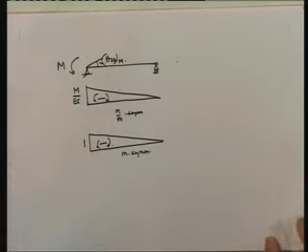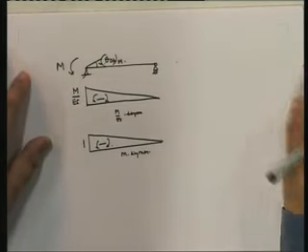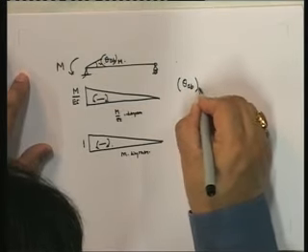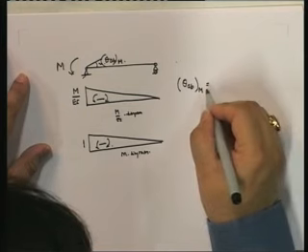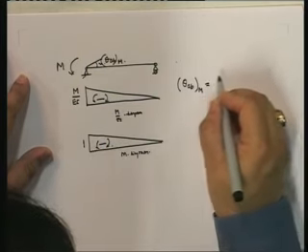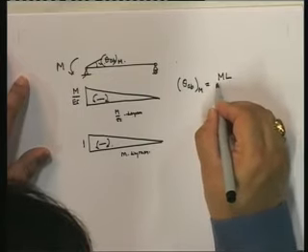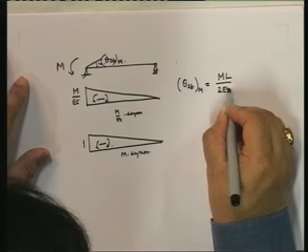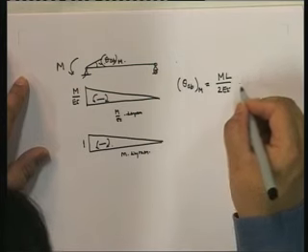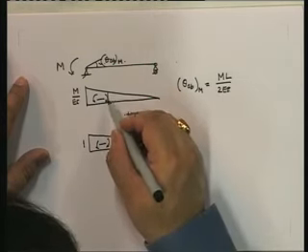I'm not writing them big because you know already. So what is the theta AB due to the moment? The area under this curve is ML upon 2EI, M upon EI into length, half of length. And where is this? This is at 2/3 the distance.